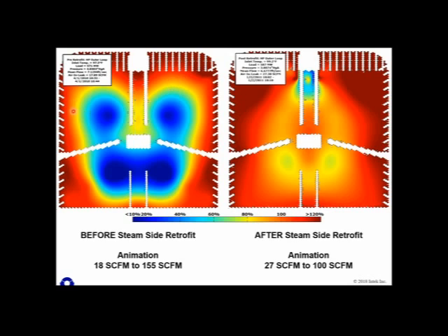But as you get inside the bundle, the velocity decreases, you get condensate loading, you do get reduced heat transfer that more closely matches the HEI values. Anyway, this scale is the HEI performance value. And as I mentioned yesterday, I like to call your attention to the yellow values. The yellow values is about a 75% heat transfer value when compared to the HEI model values, and that gives you a nice boundary bubble to put around the air bubble in the condenser.